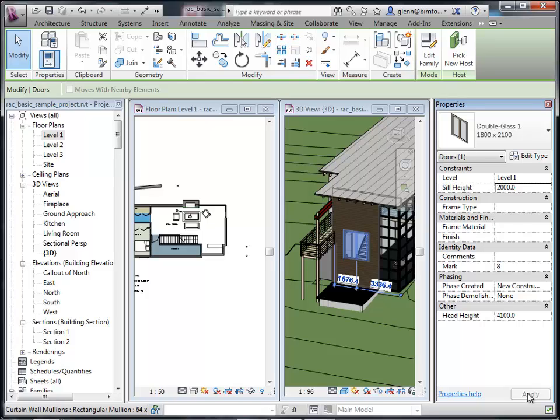It's level 1. Back. And then you're in the level 2. Actually, if I went up to level 2, we probably spot it. You're actually correct. What happens is, on level 1, since we're at level 1, and level 1 is cut 4 feet above the ground looking down, since I'm now at 2 meters, it's actually above us. So you're right. If I went to level 2, it's actually high enough now that it would be intersecting that. In fact, you want to go to level 2 and confirm. I bet it is then.